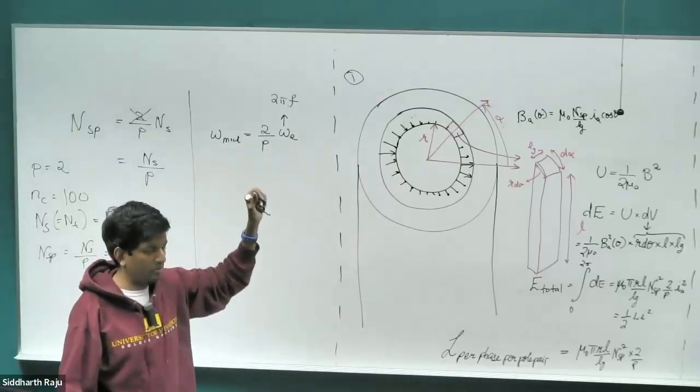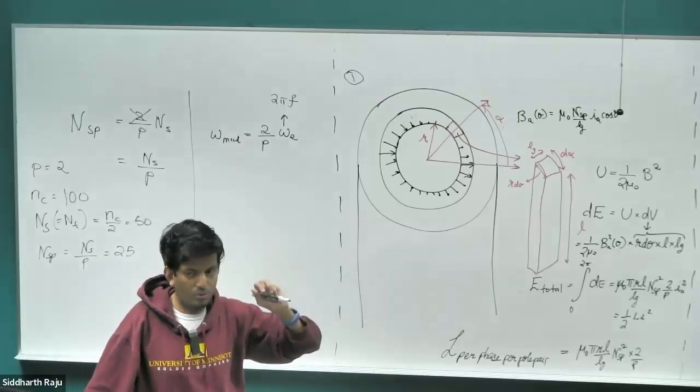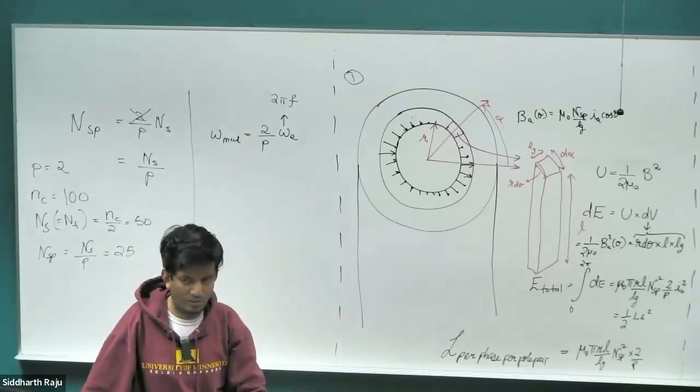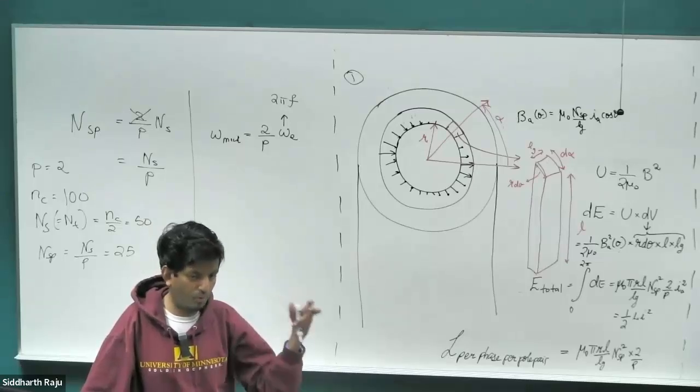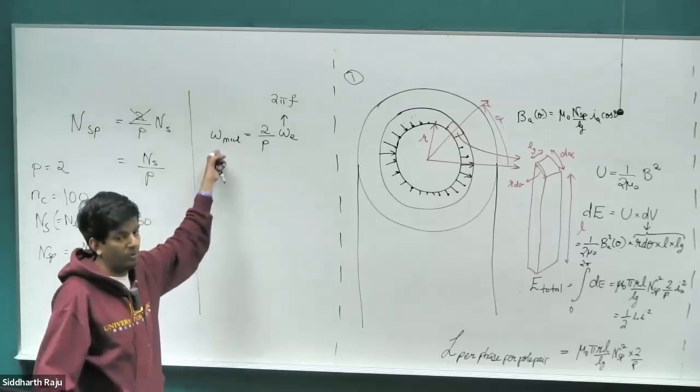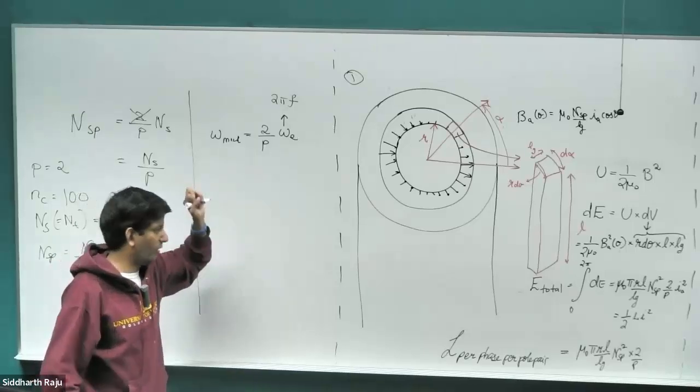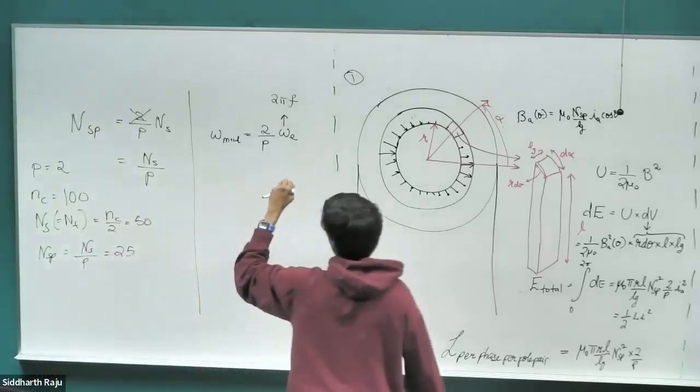But there is also another possibility that you have applied too much load torque and the rotor has come to a stop. When we do a demo, we look at that condition. In which case, that is also a steady state operating point, which is basically if the load is too large, the speed would go to 0. All right, so that's another condition. So there are 2 answers for the question. Make sure you answer both of those.